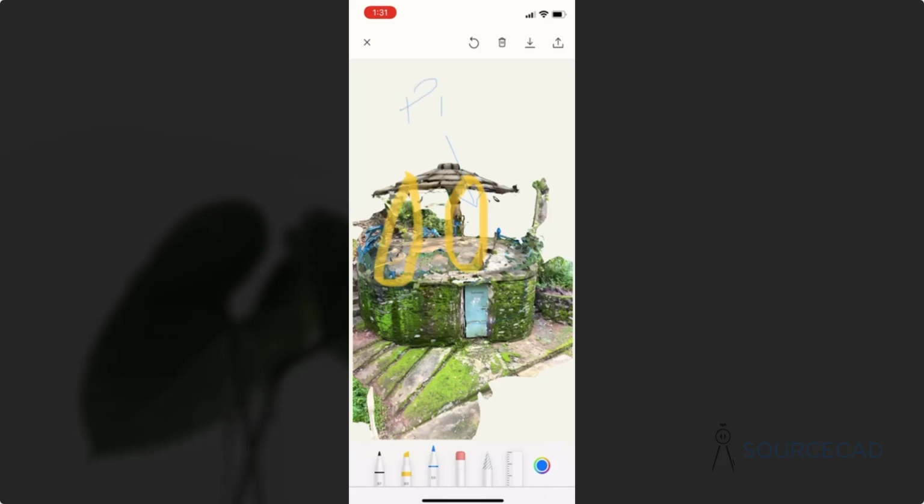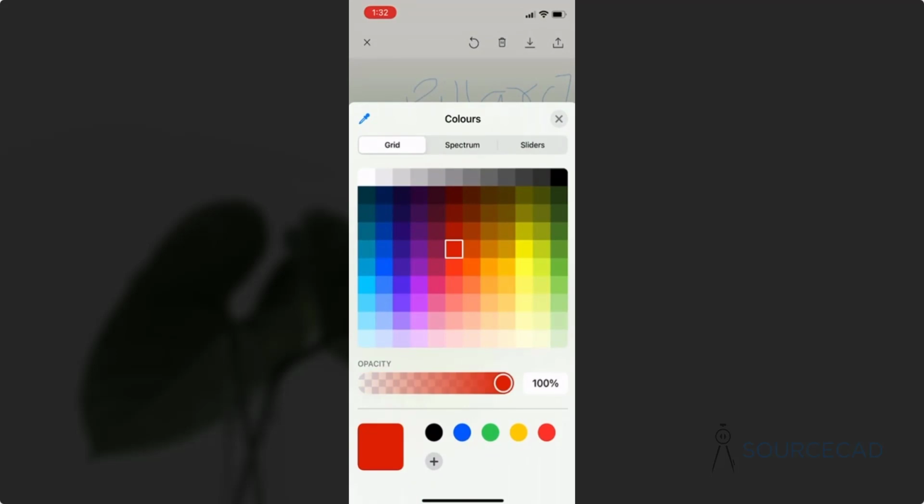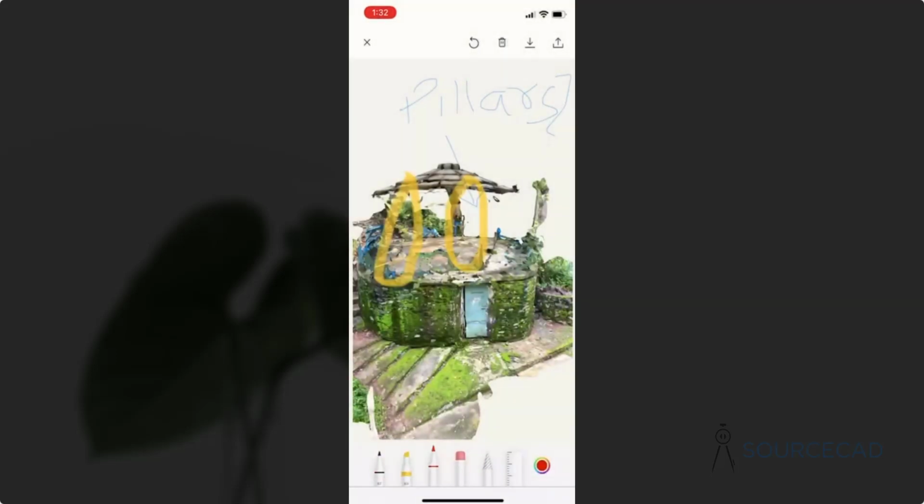Now of course you can export this one as well if you want to send it to someone else to maybe fix this one again. Now this is a markup which you can use. Now if you want to change the color, that option is right here. So just click this and then select a different color for the markup. Once you are done, you can once again go back to the pens, highlighters, and then select it and change the color. You can also erase the markups which you don't want using this erase tool. So using erase, you can simply wipe it off, like this.